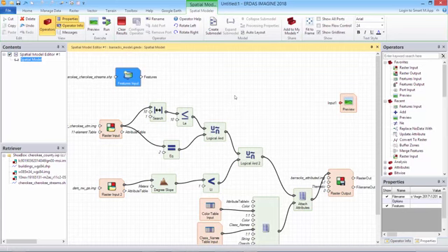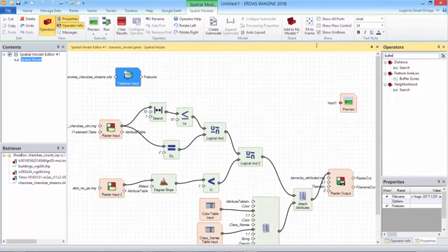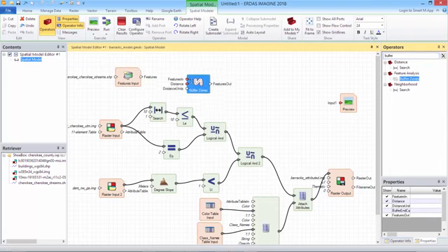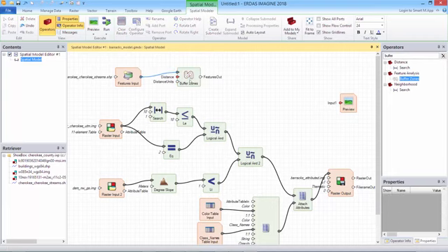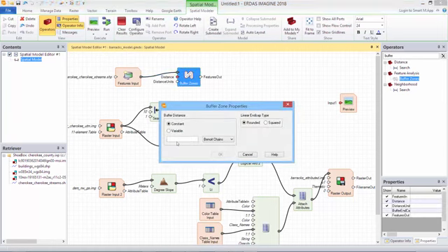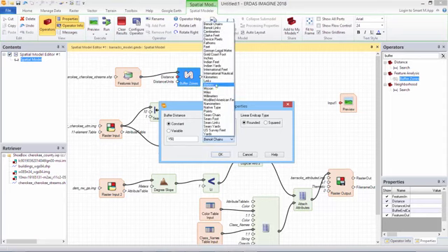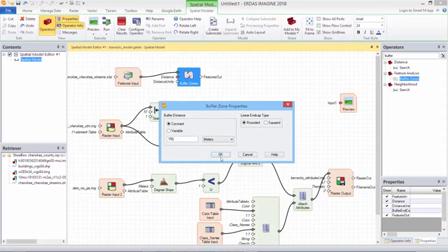Then what we want to do in this instance again is do the buffer operation, which, if you remember from the previous modules, was a raster function called search. If we're looking at features though, we actually have a dedicated features-based, vector-based buffering operation. So we can bring the features into the buffer zones operator, double click that, and I want a 150 meters buffer with rounded ends away from all the streams.